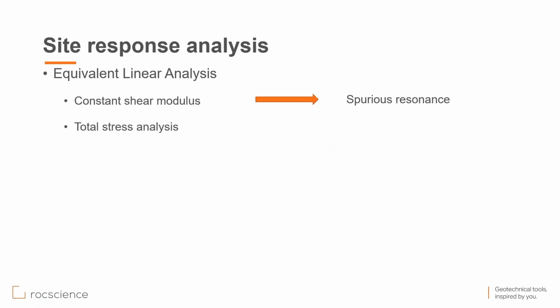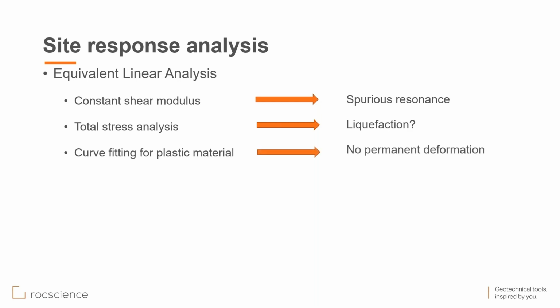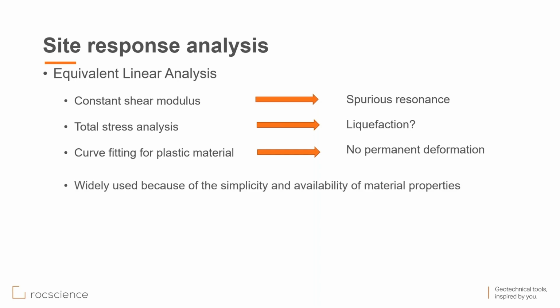Another disadvantage is that it uses total stress analysis, and problems that involve pore water pressure are difficult to deal with. For example, it is very difficult to model liquefaction using this method. Another disadvantage is that it is a curve fitting for the plastic material, and that's why there won't be any permanent deformation. However, it's still widely used because of its simplicity and the availability of the material properties.